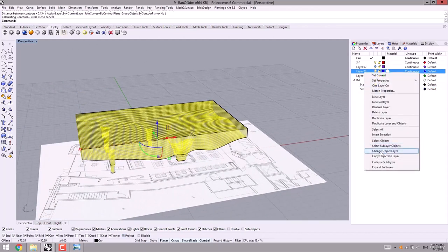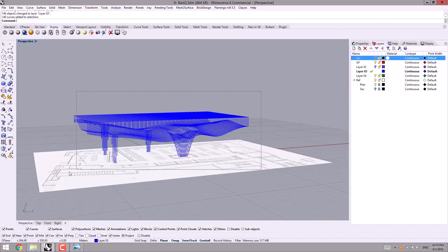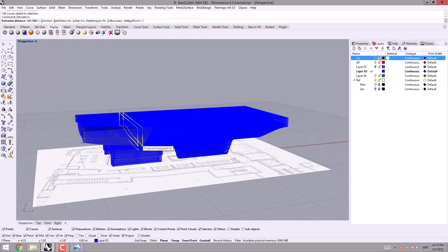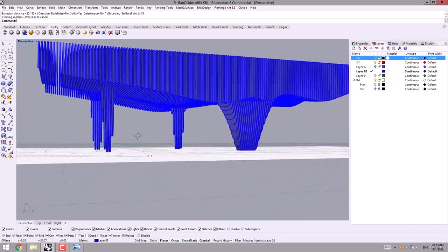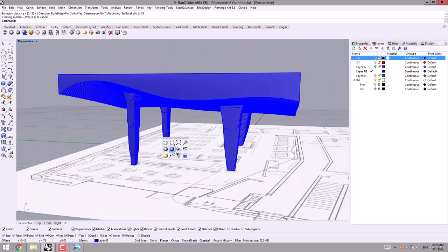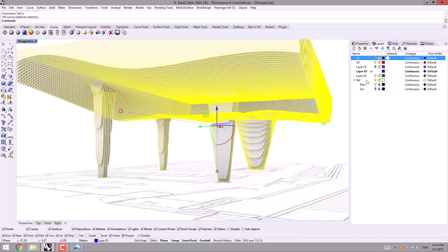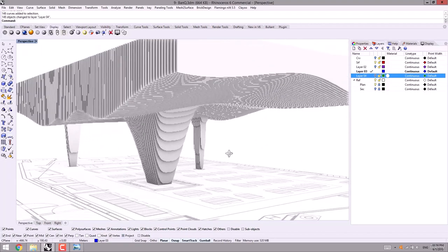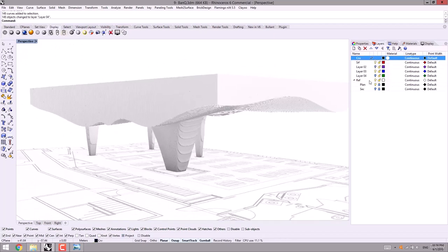Here the contour curves are created. I change the object layers, and then I turn off the previous layer, and then I select them. Then by using extrude curve, check this out, at 0.05, I extrude them at the length of 5 centimeters, as you can see. Then at the top view, I start Sel Curve command to select the curves, and then I change the object layer, and then I turn them off. So guys, by this way we managed to create the general parts of the restaurant.